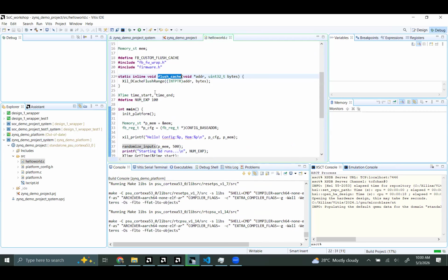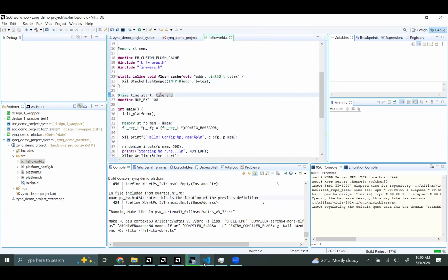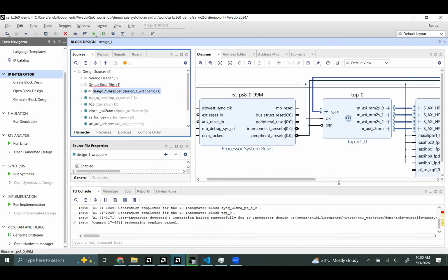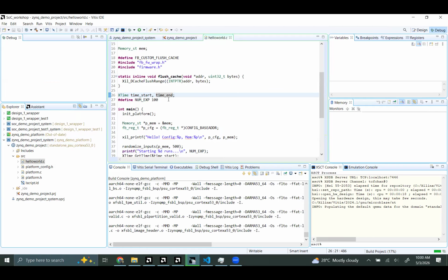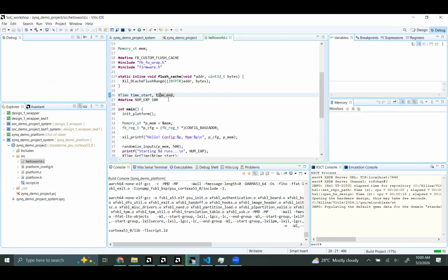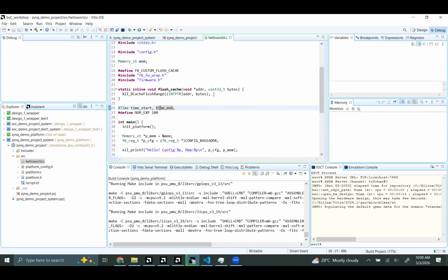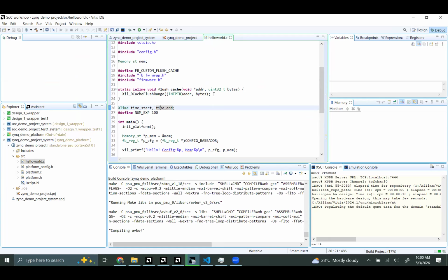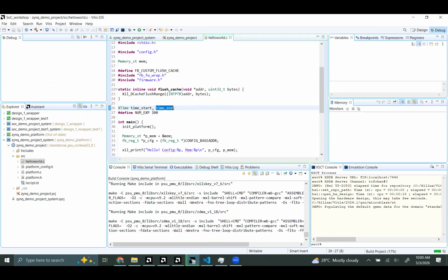First it does flush cache. I mentioned this when talking about the high performance coherent port. One of the ports we used here is a normal AXI HP port, so it doesn't have coherence. In this case, both the FPGA, our DMA controller, and the PS are trying to modify the memory. When we have done the systolic array computation, the output will be saved to the memory.